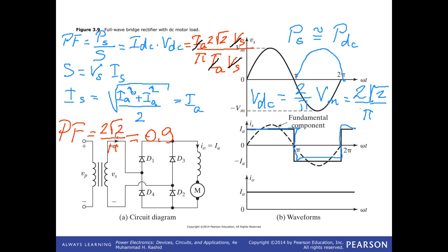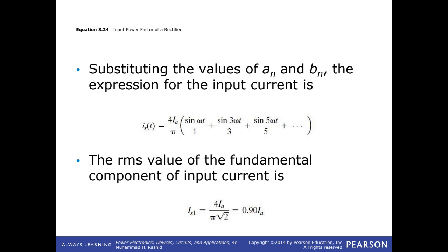Did you understand how I did it? By neglecting losses, I set the output power approximately equal to the input power. And from there I used that the RMS value is the square root of the average of the squared function, which equals itself. So I put those values in the equation here and obtained 0.9. Now there is another way too. Now what we are doing, kids, these are important concepts. I spend some time, but they are important concepts.